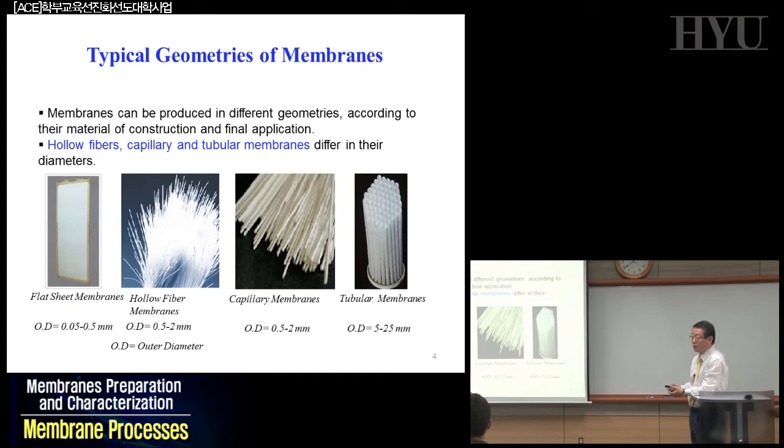This is the membrane for a membrane bioreactor called MBR, and you have the flat membrane on both sides of this module, and you pull the vacuum from the top, so that water will be passing through this flat membrane and only the pure water will come up, whereas the larger biomolecules in the membrane bioreactor will be clogged, fouled on the surface of this flat membrane.